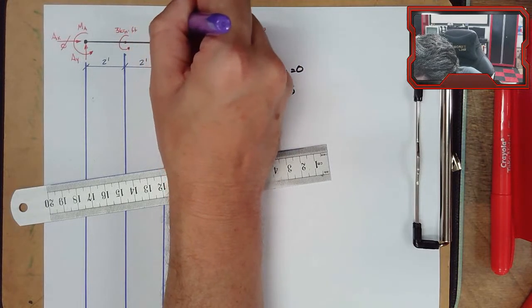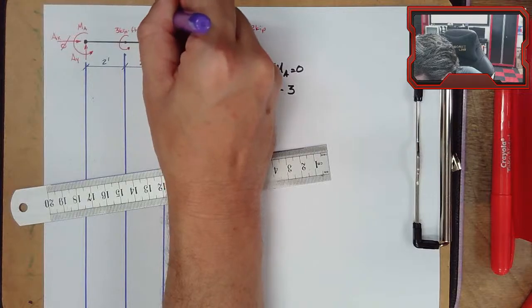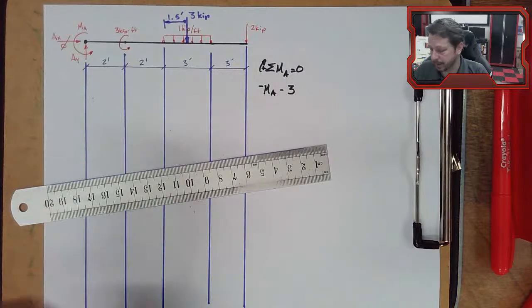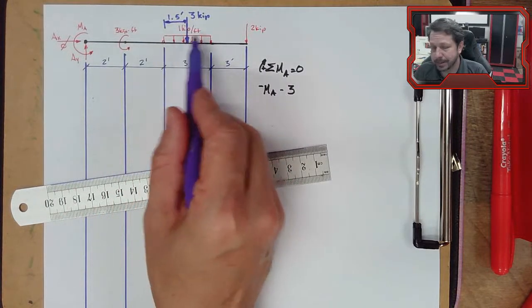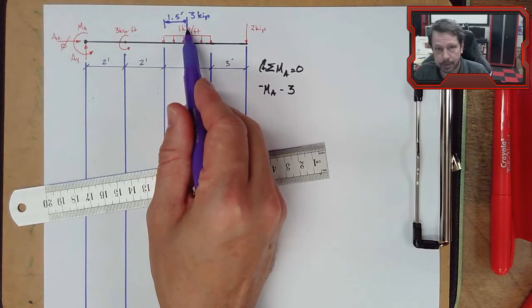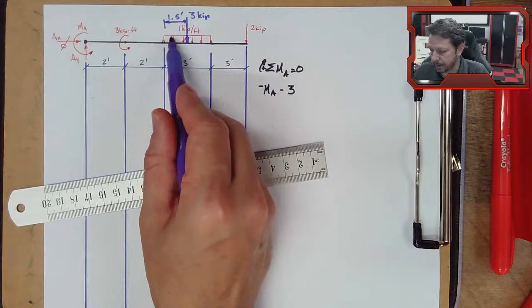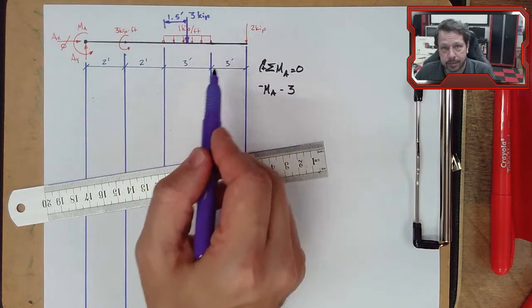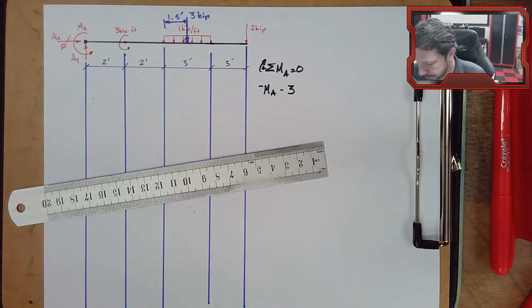And it would be set over 1.5 feet. So it's in the center of that distributed load. Is that the centroid? So if you have a distributed load that is not rectangular, you have a triangle or some other shape, then this lumped load is still the area under this curve, but you put it at the centroid of that area.